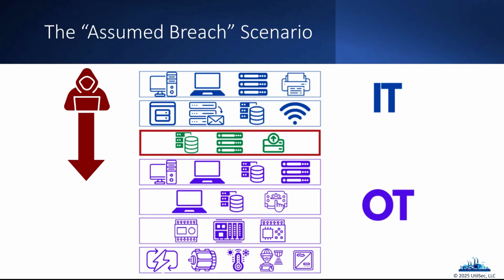When we talk about doing any type of deeper dive, that's where you're working in a test environment. Or sometimes we can actually test during what they call factory acceptance testing, and sometimes site acceptance testing. So it's before the equipment even comes on site and before it's put into a facility, as it's being built. That's a one-time you can say, yeah, knock yourself out. You can hammer away at this system as much as possible because it's not going to impact safety and it's not going to impact availability.